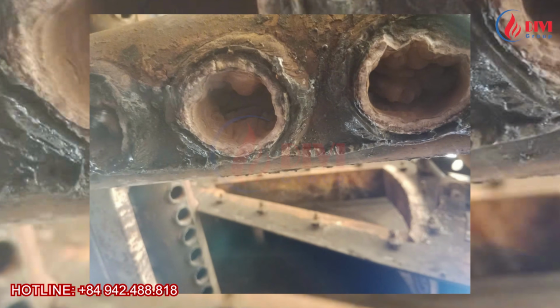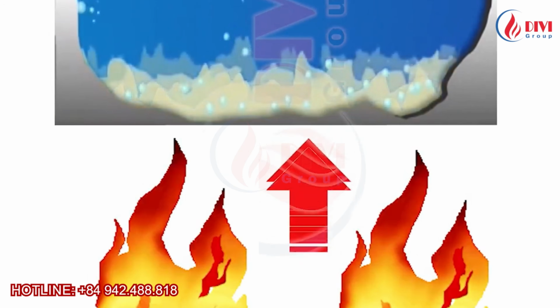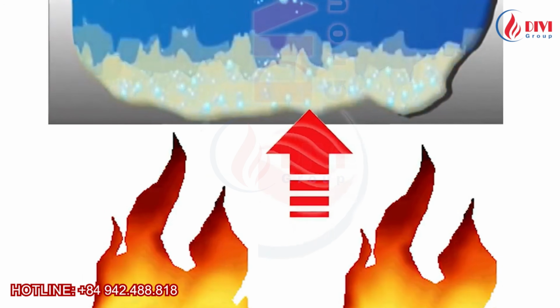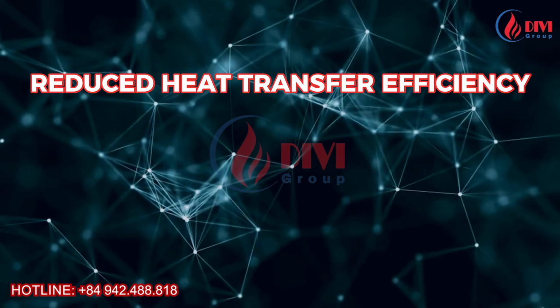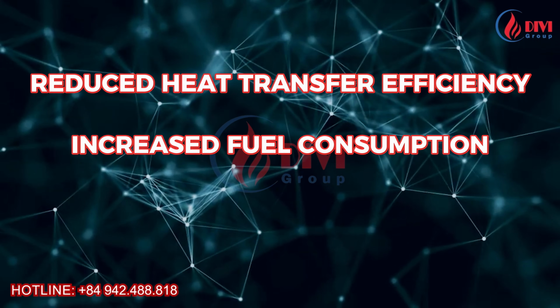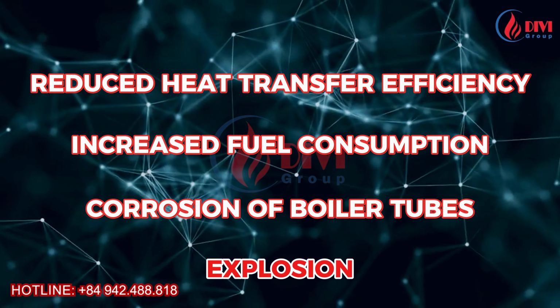Scale formation inside a boiler is inevitable during the evaporation process. As water turns into steam, dissolved minerals and impurities remain in the boiler and gradually accumulate on the inner surfaces of the steam-generating tubes. If this scale is not regularly removed, the consequences include reduced heat transfer efficiency, increased fuel consumption, corrosion of boiler tubes, and in severe cases, tube rupture or explosion.